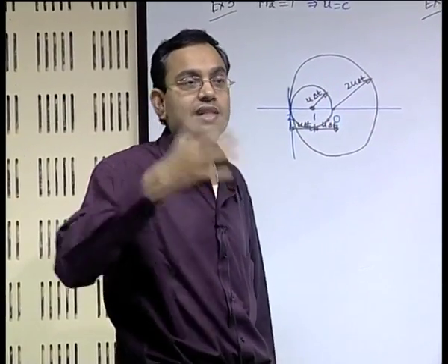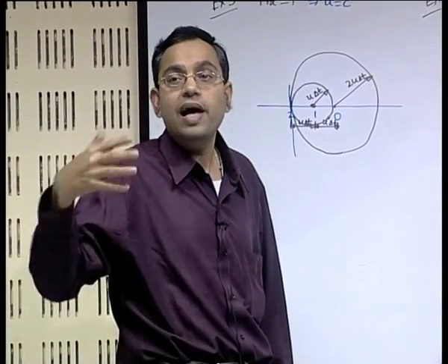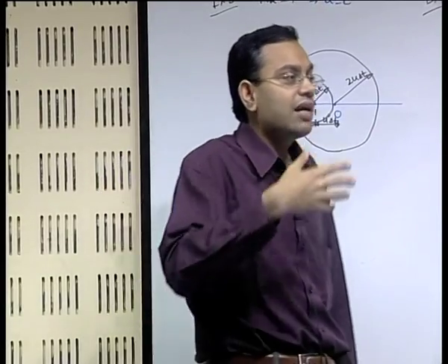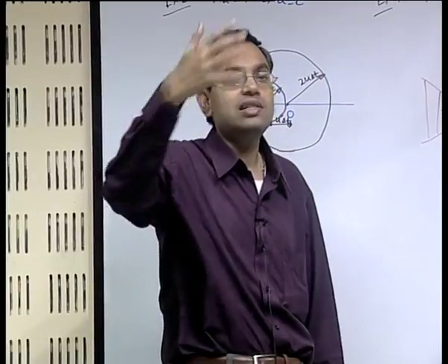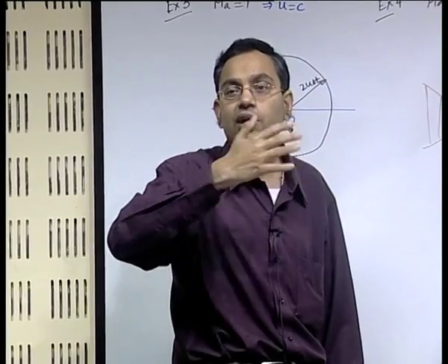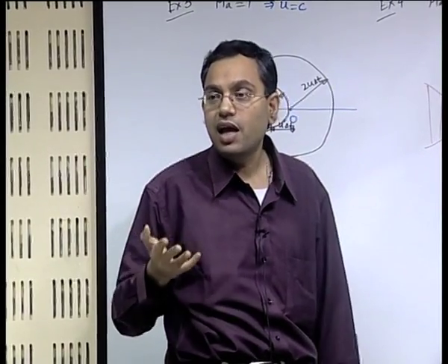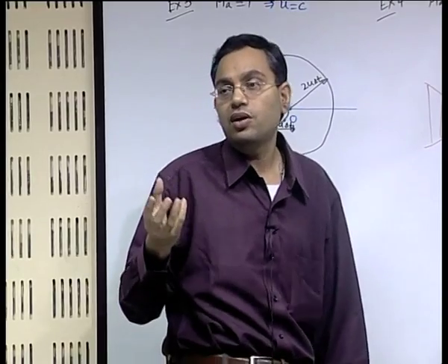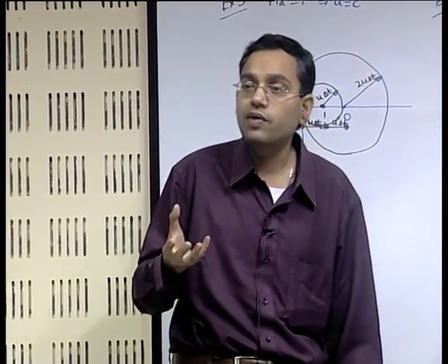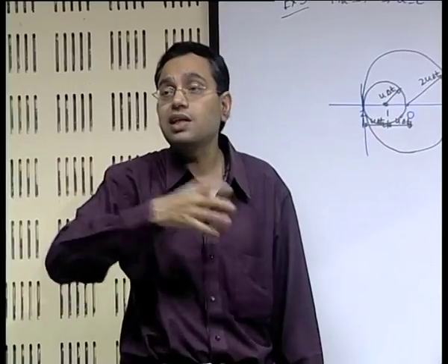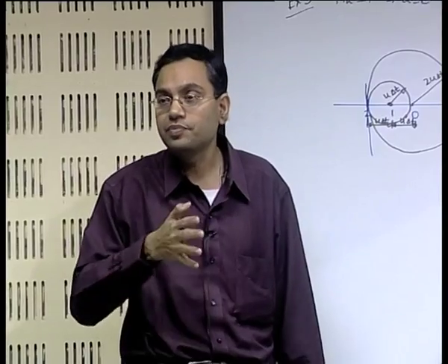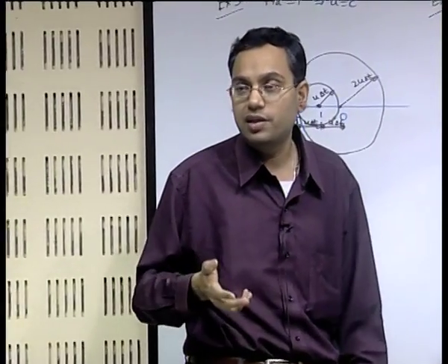The source propagates at a very rapid rate, the disturbance cannot match with that. So the disturbance tries its best to move at par with the source, but the source moves at a faster rate than the disturbance. So the disturbance is not able to get dissipated in that easy manner as it could have been possible for a case where the compressibility effect is negligible. When the compressibility effect is negligible, disturbance propagates at infinite speed. So automatically the effect gets dissipated throughout the medium at a very rapid rate.